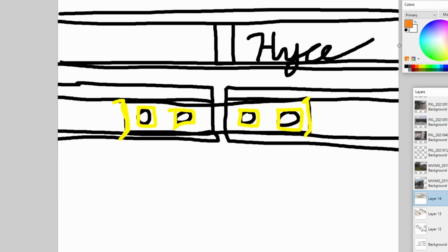But there is still a reason to have these kinds of joints, and that is a special signals purpose. We'll talk a lot more about these in the next video, again talking about special track work and signals. But the important thing to know is that they're called an insulated joint, and it looks just like one of these, except they put a special insulating material in between the rail, and it's really skinny. This is blown up for demonstration's sake. It's actually a quite small gap that they sit in. And as well, the joint bars themselves are also insulated, and so no electrical current can flow from this left rail to this right rail.